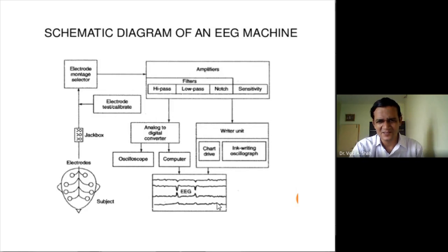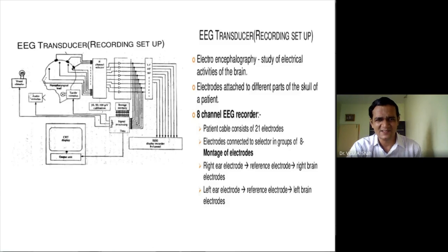So this is a computer-based system where we are measuring this through the electrodes. Electrodes are your sensing elements. Then the signal is conditioned as per the amplitude requirement. Then it is converted from analog form into digital form. Then it is applied to our microprocessor-based system or computers. And through these computers, we are generating the output, which is in terms of EEG signals of our brain. So various electrodes will sense various signals, and then we can monitor the brain's activity through the EEG machine. This is a typical EEG machine and its output.